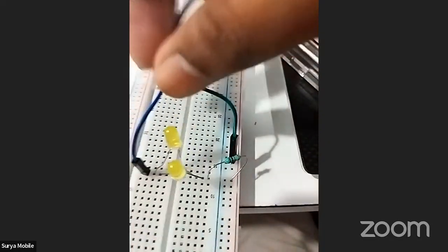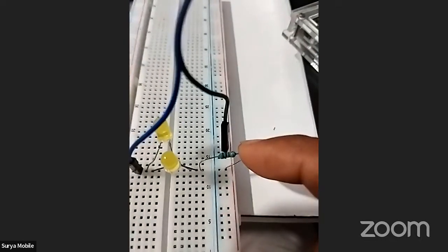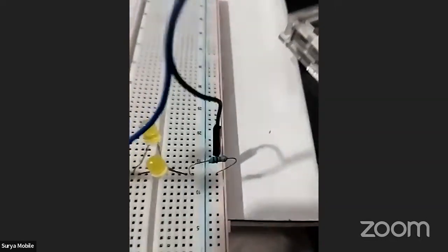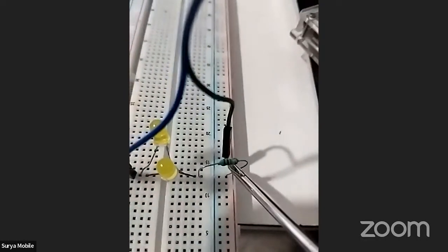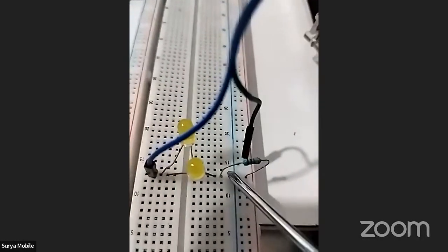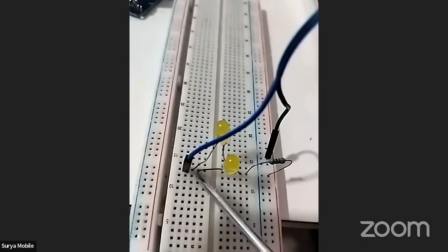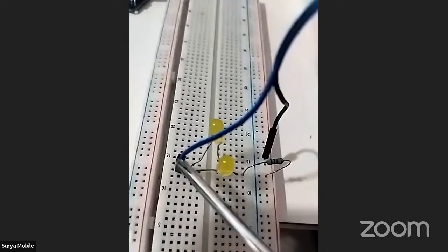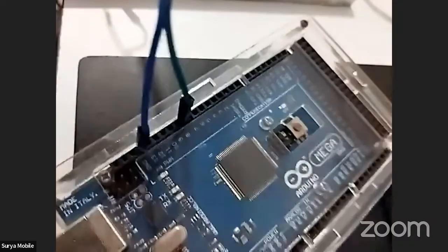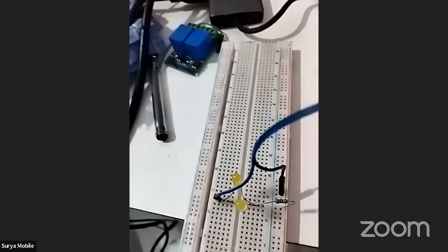Here you can see that I have connected these LEDs through the breadboard. So this is the positive terminal. Here I have connected one end of the resistor in the same line, and with this resistor I have taken it to the next level, and from here I have connected two LEDs' positive terminals here, and the two LEDs' negative terminals are connected to the negative or the ground pin. So here this is connected to the ground pin. So now let me power it up, and let's write down the code. Now I'm stopping the streaming.